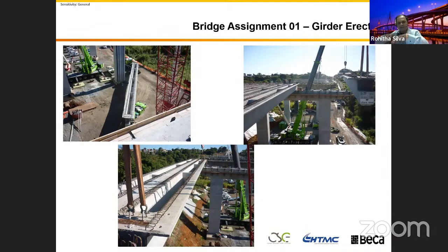The reason to select that one, because if 1.5 meter girder, if you can span only 34 meters, you are really struggling to build this one, but still you can. Because your column width is only 1.5, still you can put the pier. You can design a very special footing.